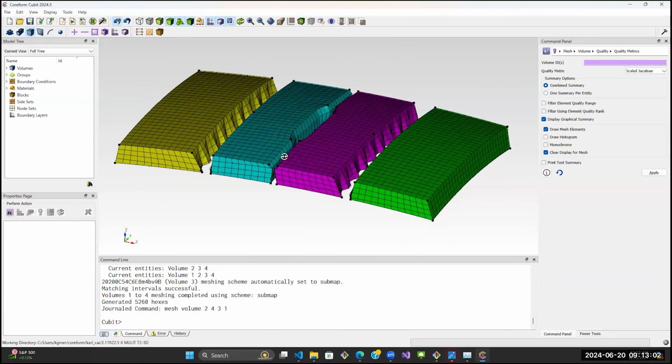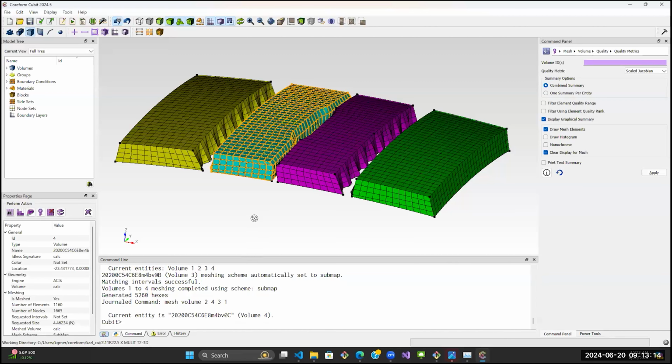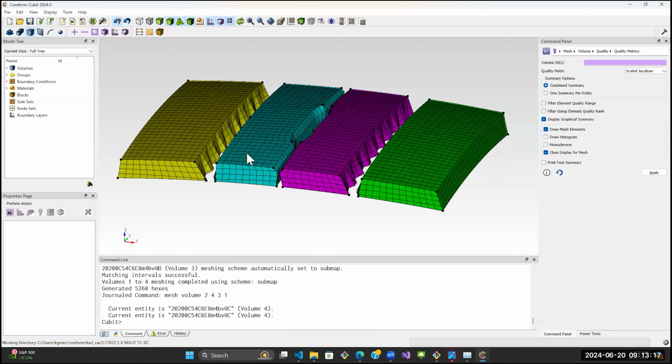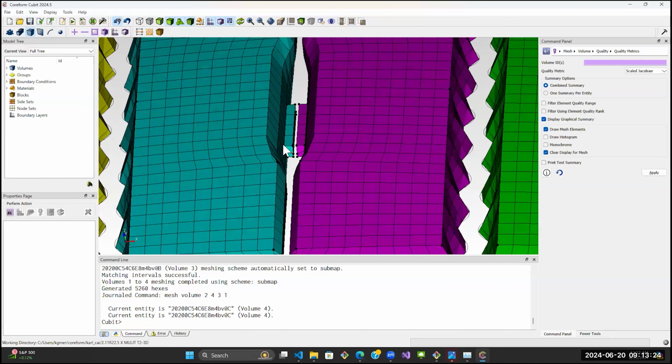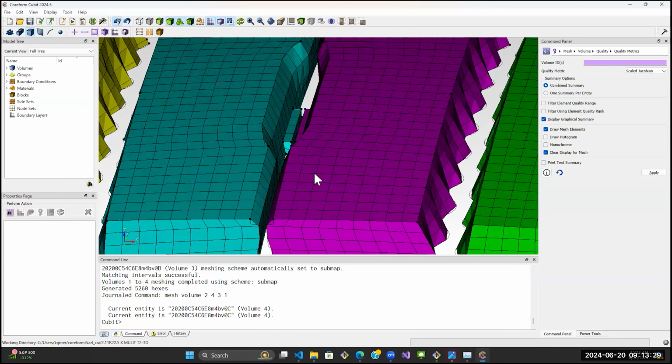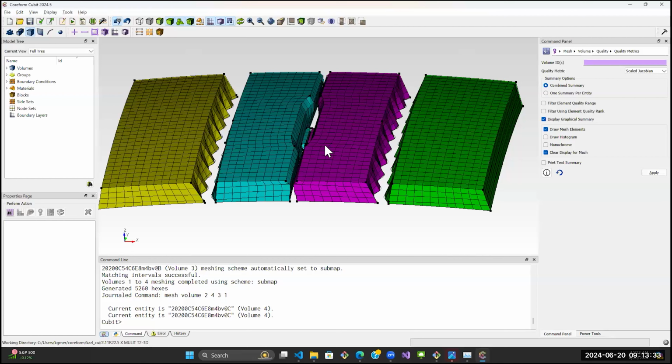So if there are questions about that, the primary thing with this model is we simplify complex surfaces in a way that we can do a sweep from top to bottom. We may have to composite the curves on those surfaces as well. Plus, we use our simplification to improve the mesh quality in those areas. And there are further simplifications we could have done on this model to improve that.